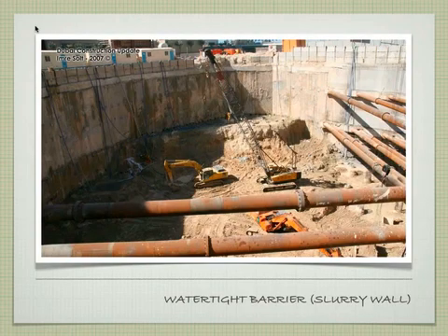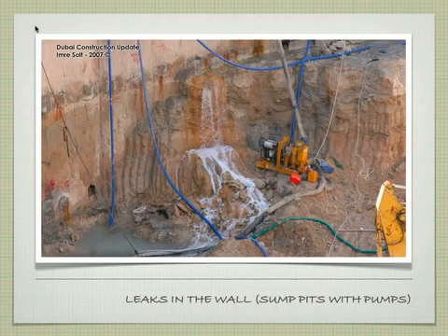So here's a watertight barrier with a slurry wall, and this is in Dubai, as an example, which has a high water table. You guys are somewhat familiar with Dubai. We've got the tiebacks working. Notice there's a little leak here, so we've got some water flowing in. So there's going to be a sump pit. I'm going to zoom in there. We've got these hoses that run up over to pump the water out. So we're doing well. There it is with our little close-up here.